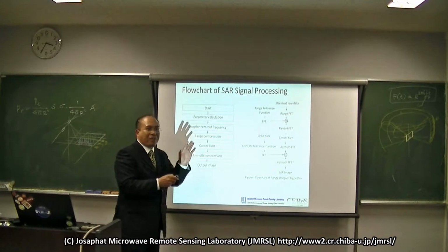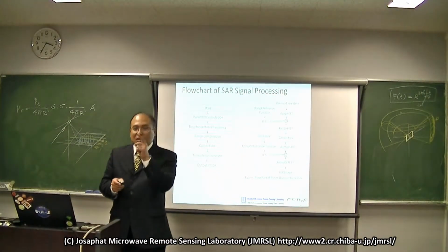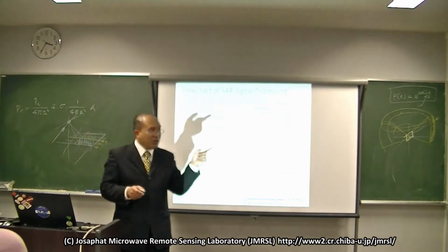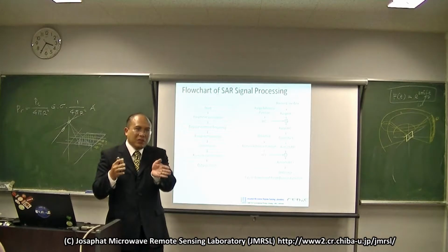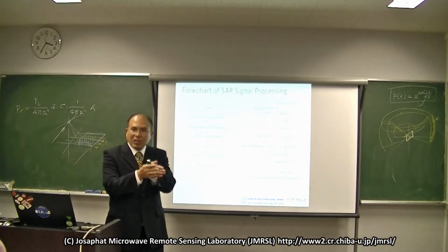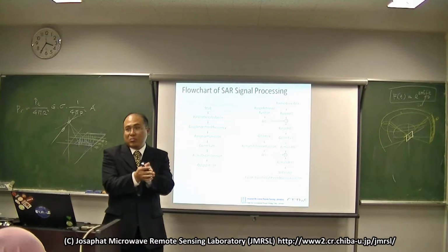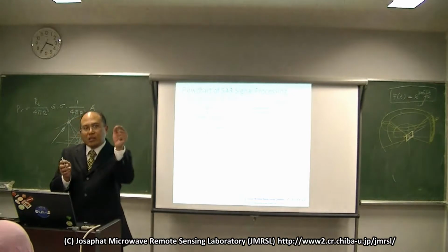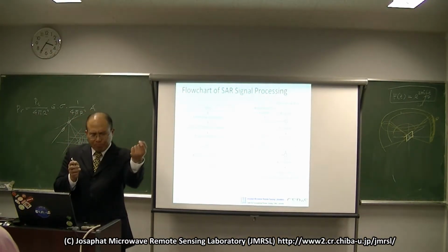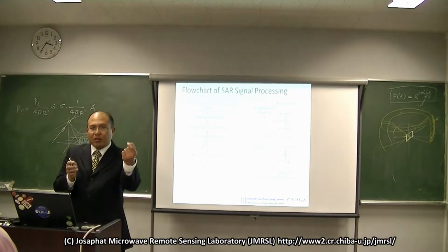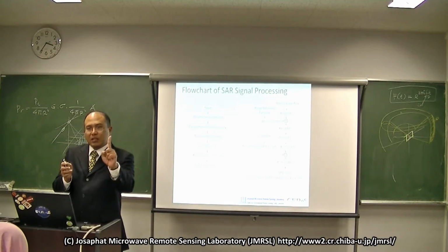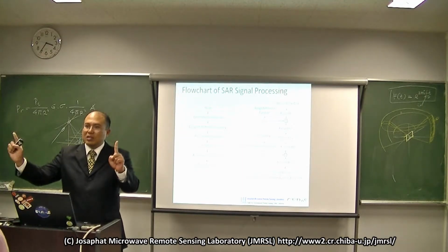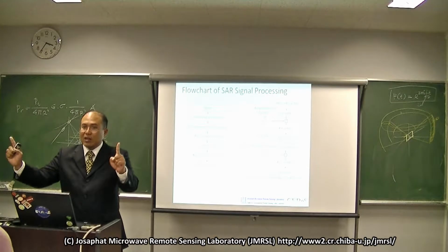And then we process with the FFT. Why do we change from time domain to frequency domain? Because later I want to explain that if we use the time domain, cross correlation consumes time and memory. If we go to the frequency domain, we can just select all the components of the scattering wave at the center frequency, with the transmitted pulse as the reference function and the scattering one at the same frequency.